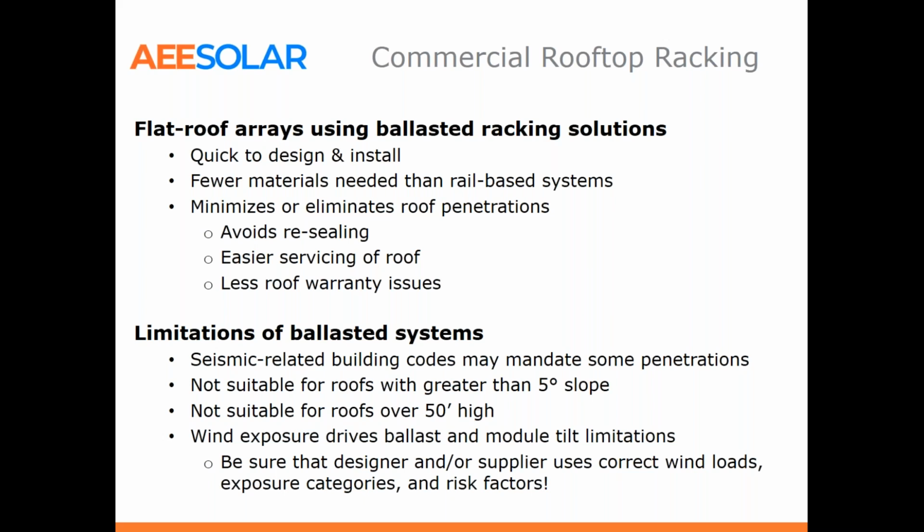There are some limitations though to using ballasted arrays. Seismic-related building codes might mandate some penetrations. Typically, it's not suitable for roofs greater than 5 degrees slope. If you do have one, let us know, and we'll see if we can do that with some penetrations. Roofs over 50 feet high tend to also break down a little bit. The ballasting starts to become really predominant and take over as you get higher and higher. The wind exposure is much more.